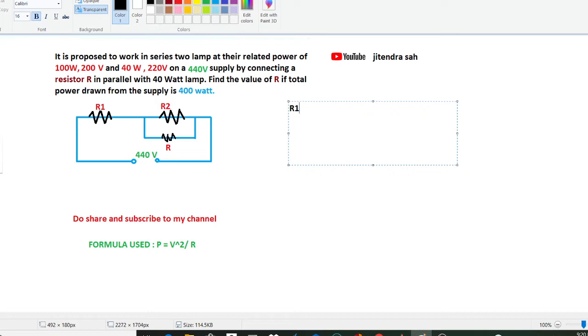Since we are using P equals V square upon R, R will be V square upon P. For the first lamp we have 100 watt and 200 volt, so R1 will be 200 square upon 100, and this gives 400 ohm.